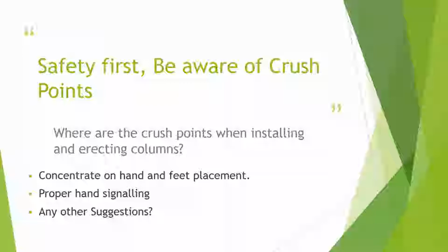All right, guys, so let's have a little safety moment now. We just discussed columns, and we gotta be aware. So it says safety first. Be aware of crush points, not pinch points, crush points. Where are the crush points when installing and erecting columns, do you think? You got to concentrate on hand and feet placement for sure. We are using our hands and feet as we're placing those columns, absolutely. They're easy to crush, and they're usually in places they shouldn't be.